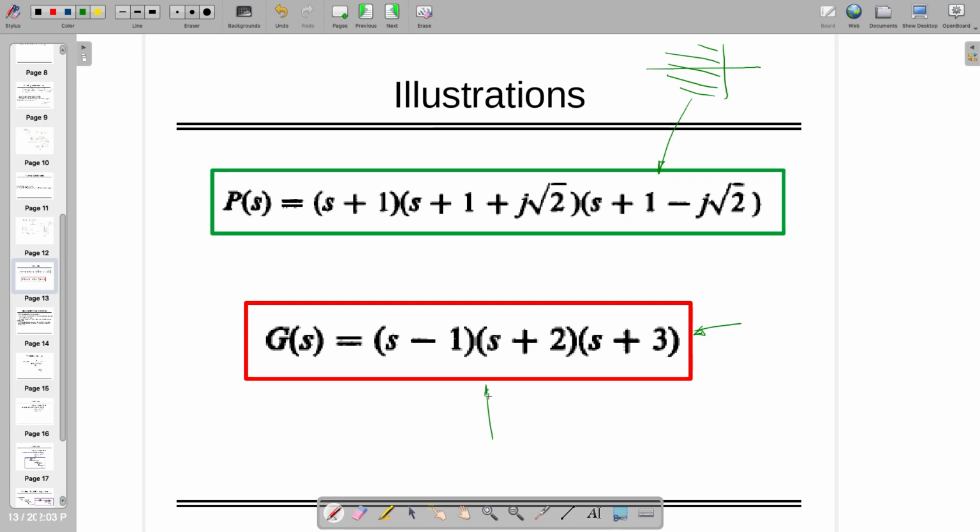This is not sufficient to say that the system is synthesizable. The first point is that all the roots have to be on the left half of the s plane, including the j omega axis, because that's marginally stable. And one more thing is, the impedances of inductor and capacitor are either SL or 1 by SC. So that is exactly lying on the j omega axis, right? It's not going to be somewhere else.